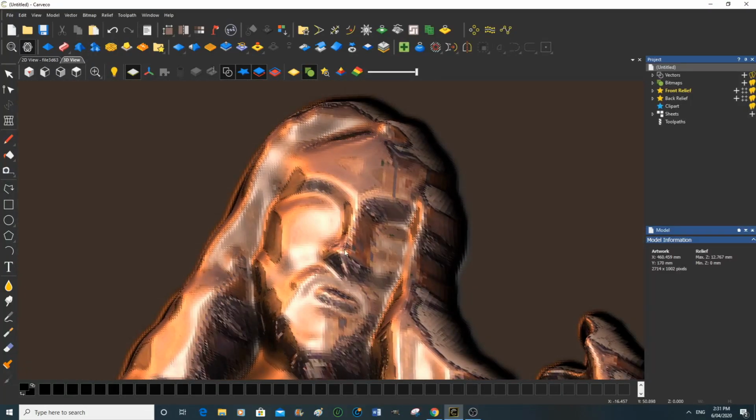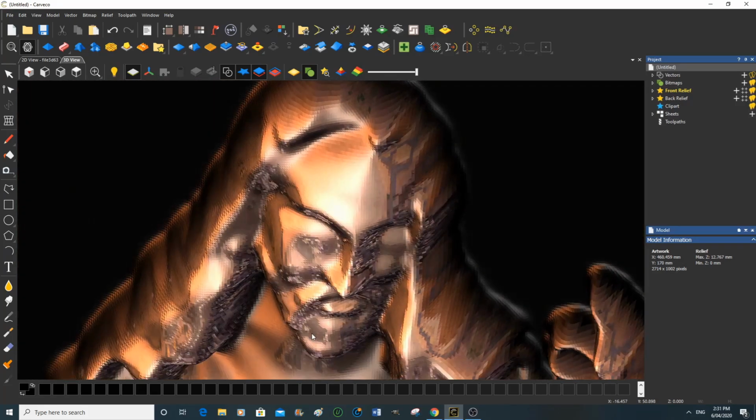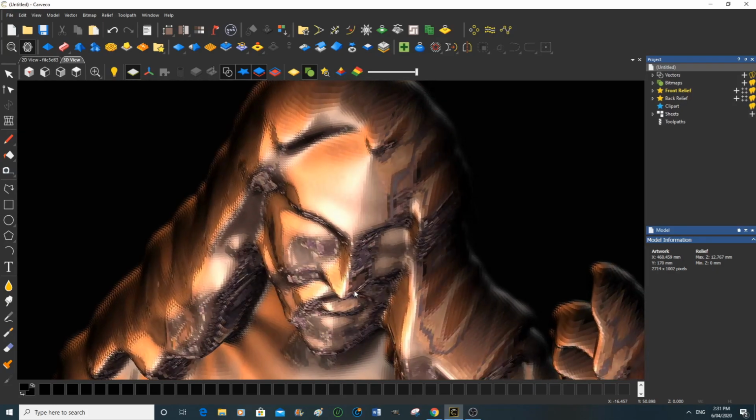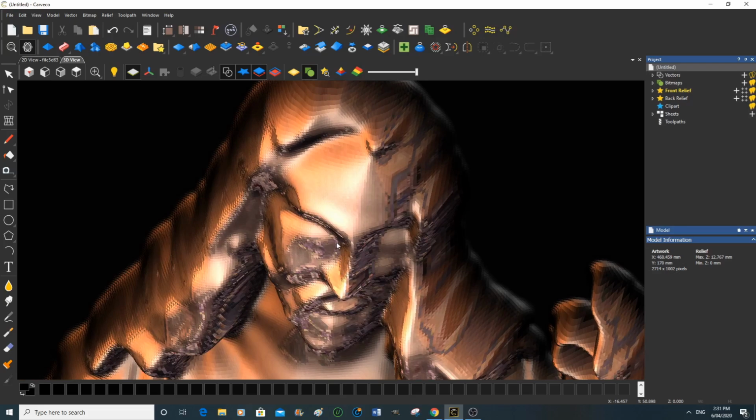Because bear in mind, from his nose to here is only probably about 1/4 of an inch. So the tool is going to come in, ramp down the nose area here, and sort of move across. It's not going to machine an awful lot, because I'm going to be using a 2mm ball mill, and that'll be about a 2mm radius in there. So it will just about get into there, I think.